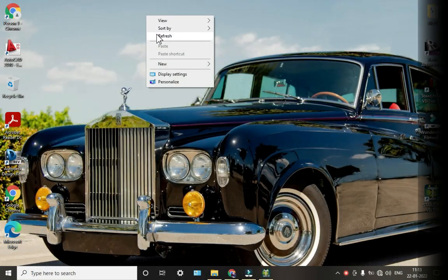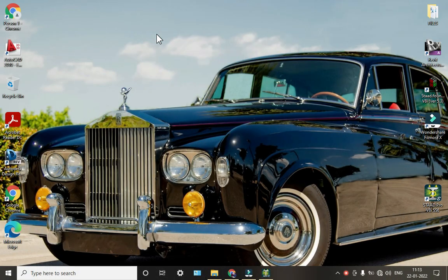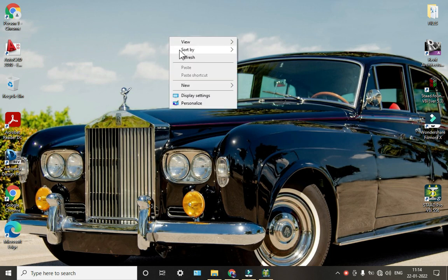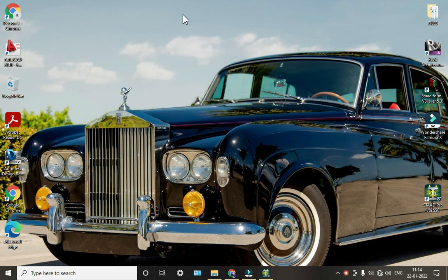Today we are going to see how to design a continuous beam and the design part by using IS456 in our STAAD Pro software, and we will apply different types of loads and take different types of supports for the beam, and we will see the displacement and how the beam will react due to its self weight.